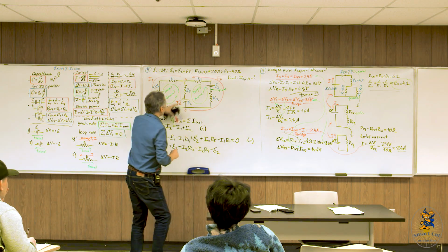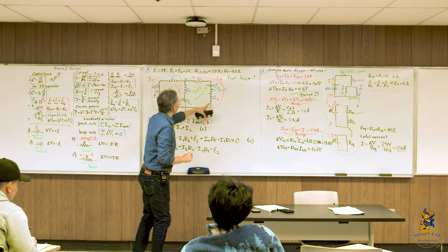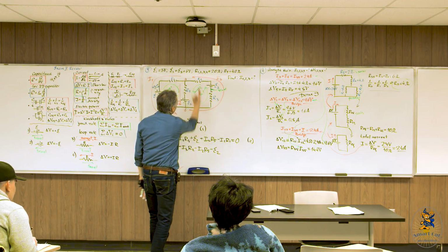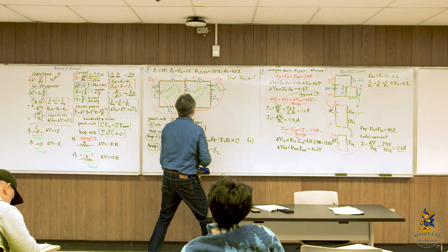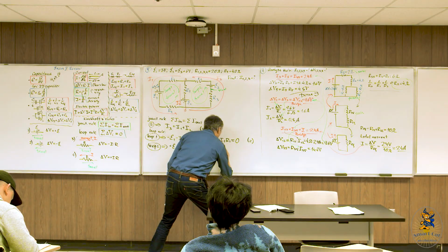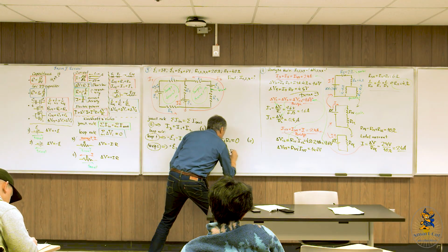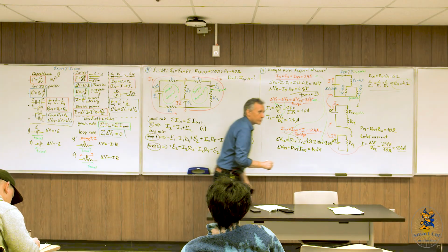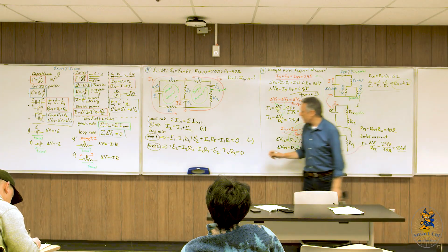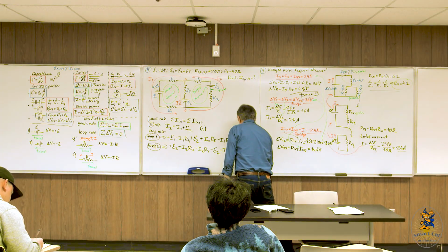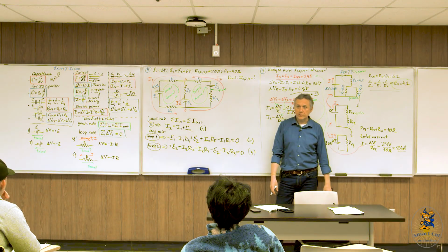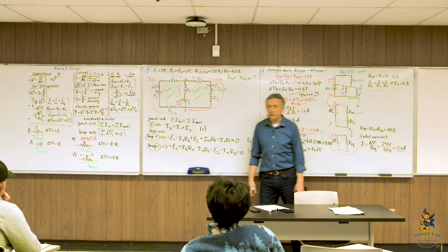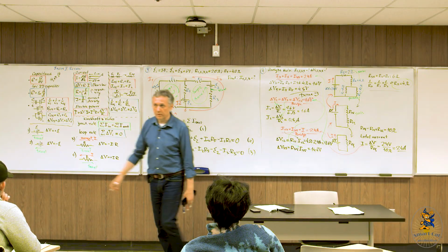Right. Okay, and after this, we're going across this resistor. Travel up, current up, directions the same. Contribution is negative, so it's a minus I3 R3. Okay, and again, it must be equal to 0. Equation number 3. So now 3 equations, 3 unknowns, physics is over. So nothing else. We applied all the physical ideas, physical concepts. The rest is just mathematics, just simple algebra.